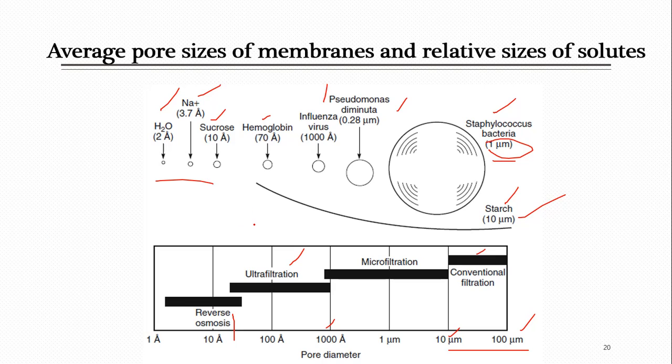So from here you can get the idea when you look at various filtration plants. Suppose you are cleaning water, and the water contains various contaminants and impurities. Before bringing your water to the final separating membrane, you can remove various components by using other membranes or filters. This will help to decrease the load of pollutants on our last membrane. Later, when we talk about reverse osmosis in detail, we will talk about the various problems which take place if you don't do these prior filtrations.